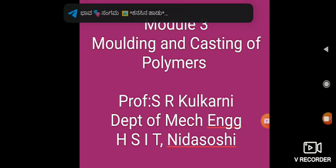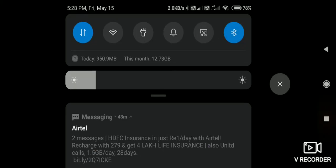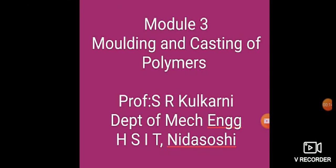This is pertaining to the molding and casting of polymers. Blow molding. The first one is blow molding. Blow molding covers the three main thermoplastic processes: extrusion blow molding, stretch blow molding, and injection blow molding. Extrusion blow molding is the largest of the three, followed by stretch blow molding and injection blow molding.